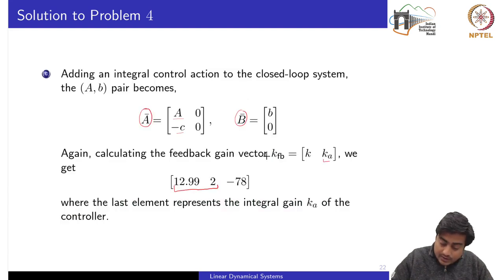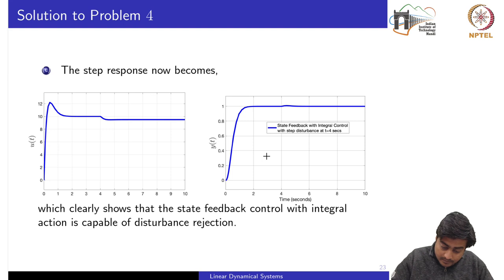Okay, and you can use either of the methods, the eigenvalue assignment method or the Lyapunov-based method. So now if we pay attention to the closed loop signals of the system on which the disturbance is acting, you see when the disturbance is added at t equal to 4, the output almost tracks the reference signal now. Because of this new structure, we are able to reject the effect of the disturbances on the output signal y, and this happens, we know already, implicitly, because of this integral action, which is able to diminish the error between the reference and the output.